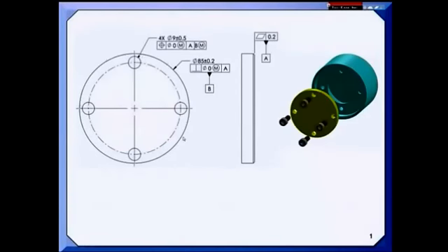If the outside diameter is made closer to its lower limit of size, I would be able to shift it around inside the case at assembly in order to get these screws to go in the clearance holes. And for that reason, I've put an M here on the datum feature. Now, that doesn't mean that I get more tolerance on the position of these holes.